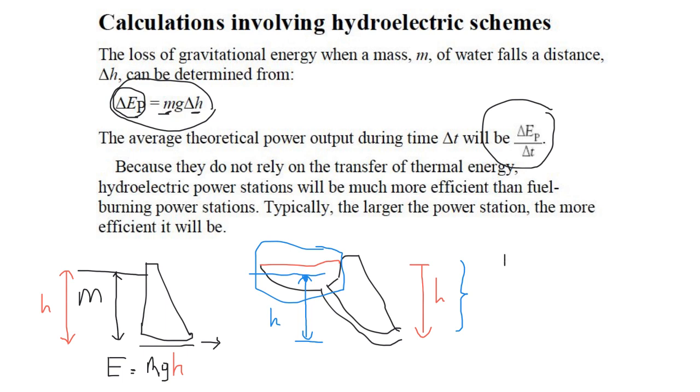And then thirdly, remember that mass can be found from density times volume. Most of the time you're given a value for density and volume instead. Now, what's important about this is that you check that your units correspond. So density is kilograms per meter cubed times volume, which is obviously meters cubed. So if for whatever reason, which is unlikely, but it could happen, you're given one of those in centimeters cubed, remember to convert it.